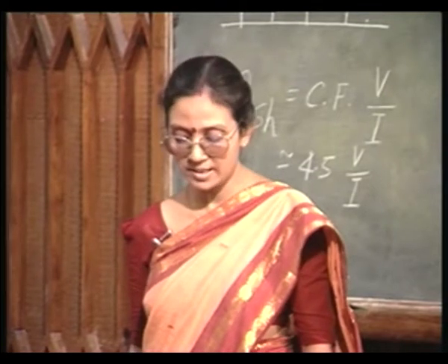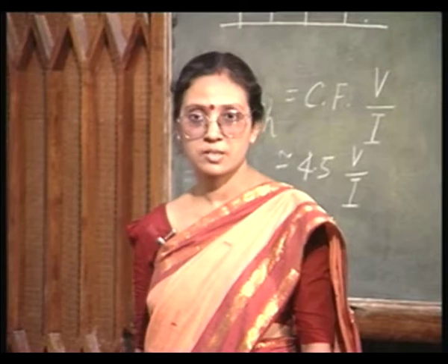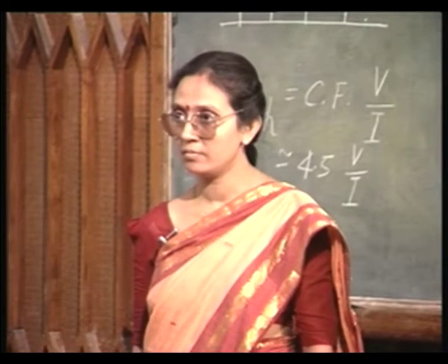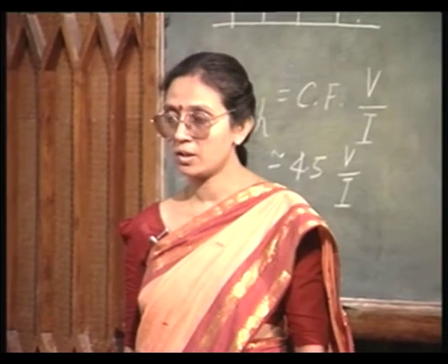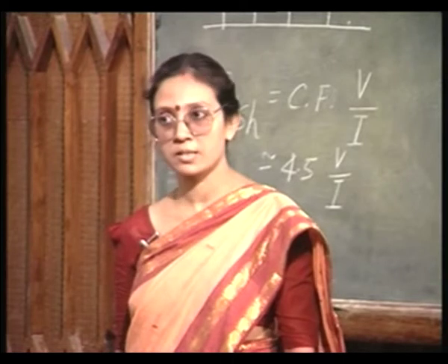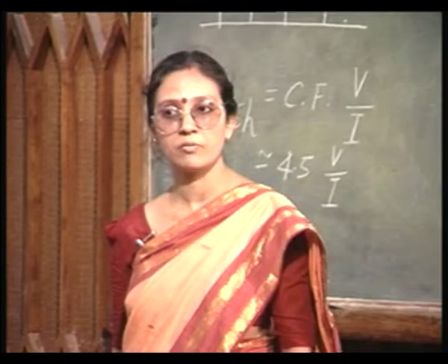So, the difference in these two sheet resistance values will be related to mu times n, right. It will actually be given by 1 upon q mu n into dx, the difference. You know dx, dx is the amount of silicon you have consumed.